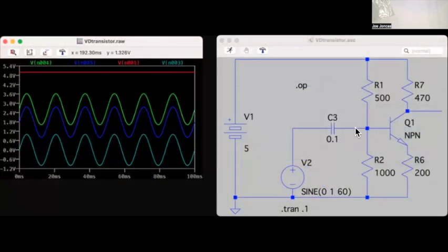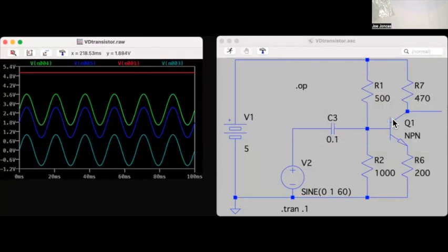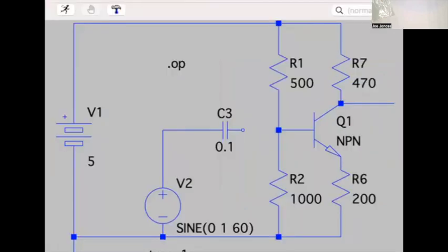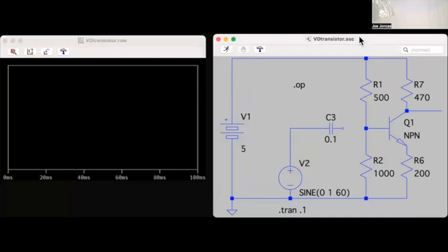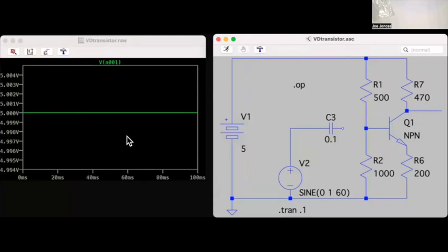Let me delete a couple things. I'm going to cut that wire. I'm going to close this. I'm going to restart it. Okay, now I come back over here. Now I'm going to look at the voltage coming in, and we can see that's 5 volts. And if you remember this point here, I had 2,000 ohm resistors, and I figured I'd get it close to 1.5 volts.